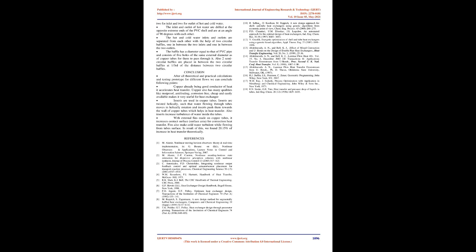Also, inserts increase turbulence of water inside the tubes. With external fins made on the copper tubes, the contact surface area for convection heat transfer increases. Fins also make cold water turbulent while flowing over the tube surface. As a result of this, we found a 20.15% increase in heat transfer theoretically.